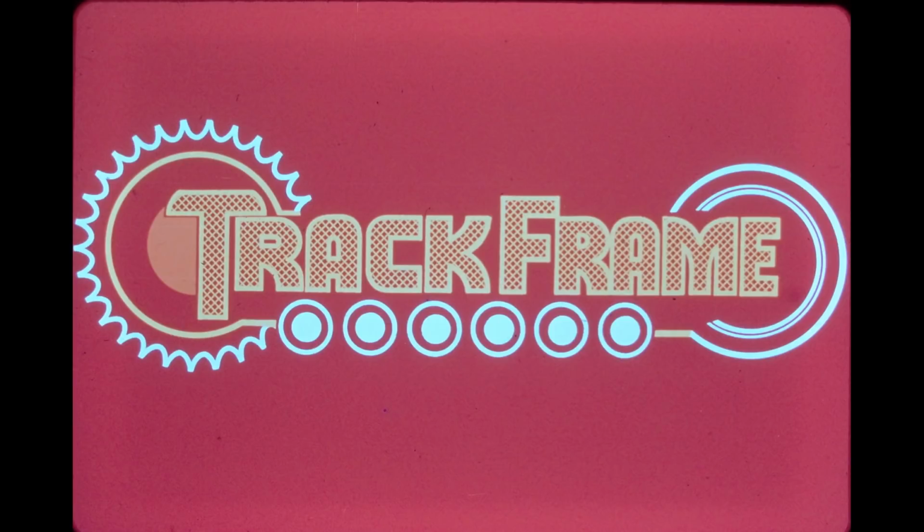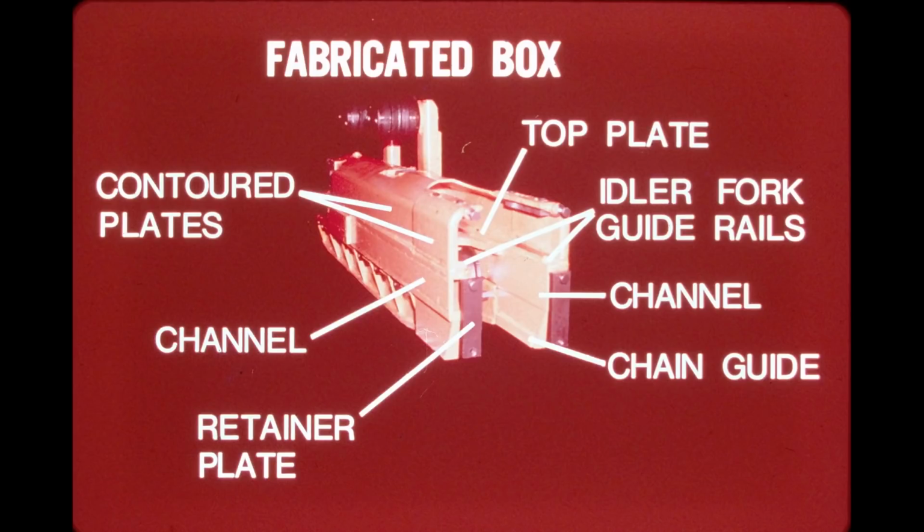As was mentioned before, the track frame is the foundation of the undercarriage, providing a mounting or housing for other undercarriage components. International uses two basic types of track frames: fabricated box and fuselage. The fabricated box design, with minor variations for the various models, consists basically of two heavy steel channels bridged with a thick top plate.